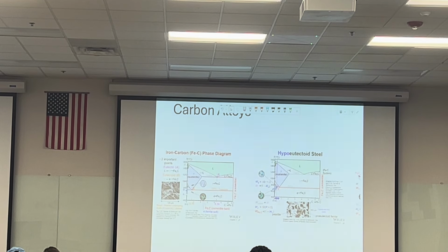Those are the eutectoid structure. Any questions? All good? You're going to have the diagram itself, but not the structure. I'm just saying, what does it mean when it says pro-eutectoid? It means the alpha phase that has been formed before entering this region. And eutectoid is the alpha or cementite which is formed after entering this region.